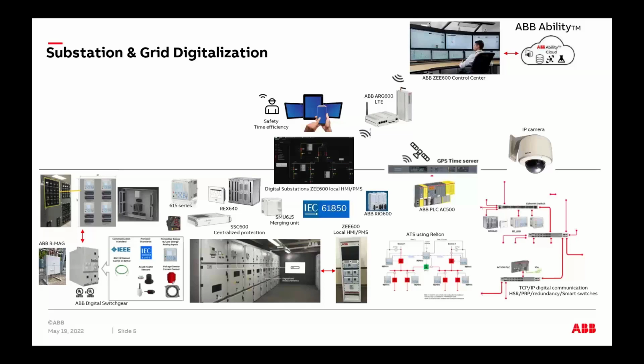So you're looking here at the same time, I'm doing all this digitalization, and then once you're done, you're going to say, okay, I have all this now fancy substation, for example. How do I pull that data? What do I need? The type of HMI I'm going to need, and if my HMI, or let's say we call it a power monitoring system at the substation level, how do I pull that data, and how do I also design that HMI in such a way I will pull all this data from every single device, and how do I manage all those signals?